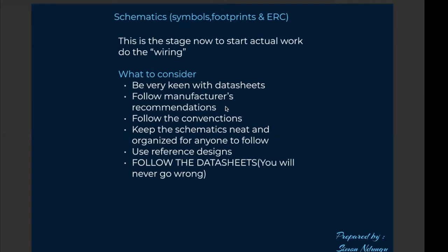Use reference designs. I've talked of reference designs: say you want to design something like a power supply, just check something similar that people have done and posted. Check what other people had done, get some insight, apply it in your design. And if you follow all these and look at the datasheets very well, you'll never go wrong.